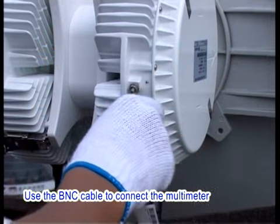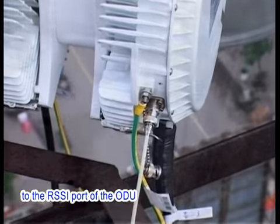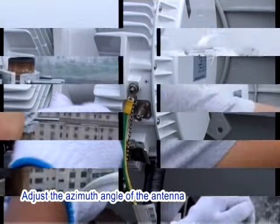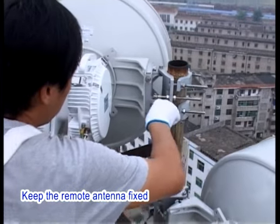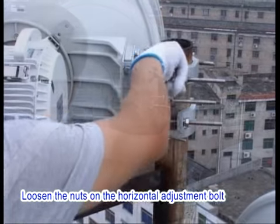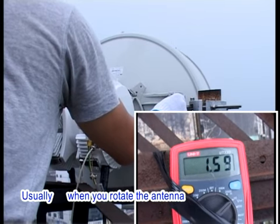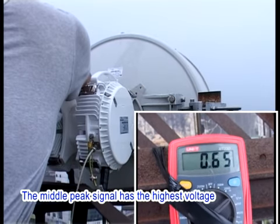1. Use the BNC cable to connect the multimeter to the RSSI port of the ODU. If there is no BNC cable, you can connect the multimeter directly to the RSSI port of the ODU. 2. Adjust the azimuth angle of the antenna. Keep the remote antenna fixed. Loosen the nuts on the horizontal adjustment bolt of the local antenna. Rotate the antenna around the pole. Usually, when you rotate the antenna, 3 peak signals can be obtained. The middle peak signal has the highest voltage.